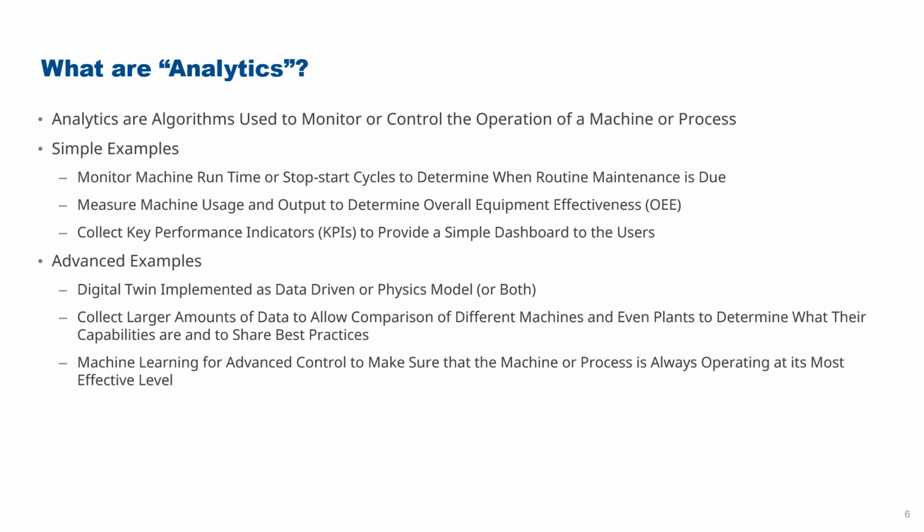So it might be your digital twin is operating differently to your actual machine, and that could indicate that your machine has degraded operation. Maybe there's tool wear, maybe there's something that's causing issues, maybe there's a raw material difference. But the idea of a digital twin, this gives you a very good, accurate model of how the machine or process should be operating and allow you to compare that against how it actually is operating.